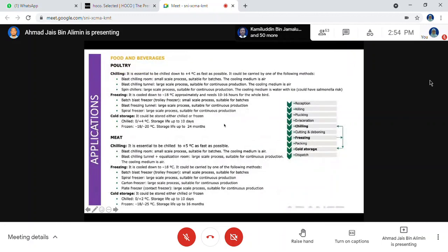So the engineers, or the refrigeration system designer, they need to work with the industries. Okay, if you are dealing with poultry, then this is your range of operation. So if this is the range of operation, what will be the required mechanical system, the compressor, the throttling device, the condenser, and so on.